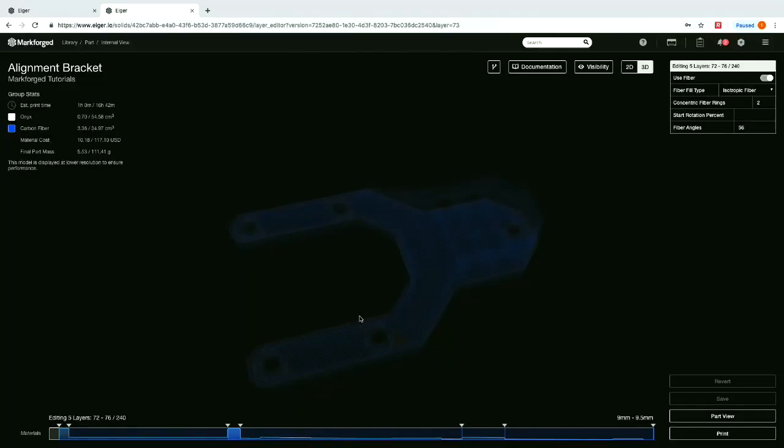Yep, and I would say your point is true, and it rings even truer with the fiber because fiber parts are even more anisotropic than your typical 3D printed part. You're really reinforcing 2 axes in a serious way, and you're leaving the third. The z-axis tension will not change.